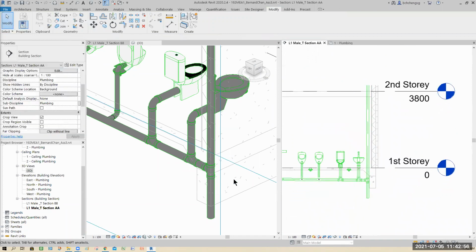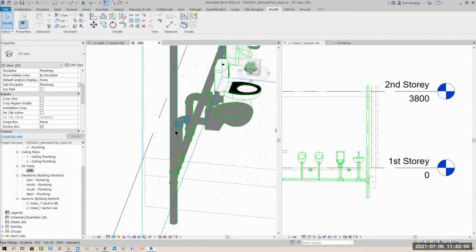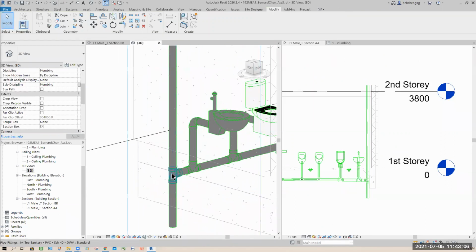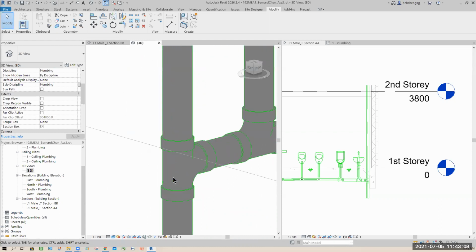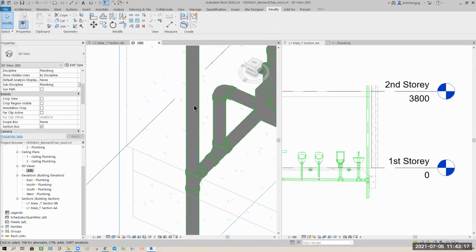But right here should have something for us to clear the choking. In Singapore, if the pipe is big enough, our design has an opening to clear the choking. But because this is a small pipe, they have to add some fitting here to act as that opening.